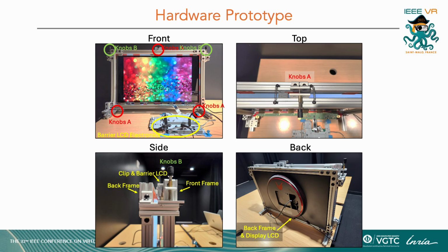Following previous works on light field displays, we build our hardware prototype by stacking 2 commercial LCD panels rigidly. The front panel modulates light and acts as a parallax barrier, and the back panel displays the content image. By switching the barrier patterns and display images at 240 Hz and a time multiplexing factor of 8, a display rate of 30 FPS is achieved. Please see the paper for more details about the algorithm and hardware implementation.